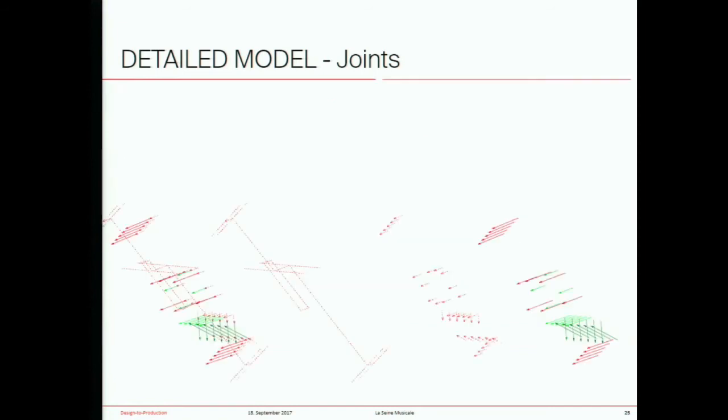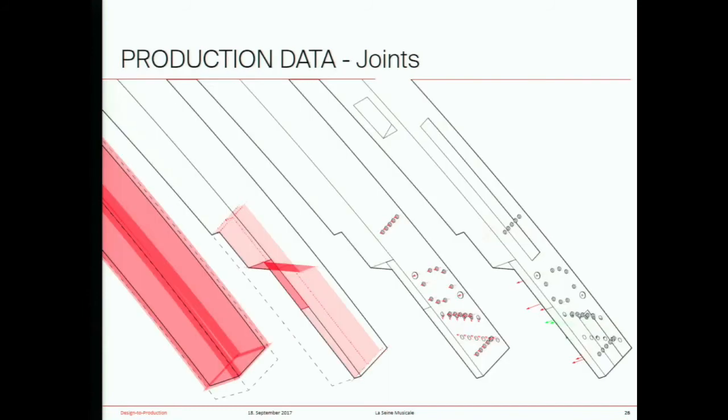At the end, all the operations are placed in the model at the reference level, which means that there's no margin applied yet. Instead, these tolerances are stored as attributes on the piece in order to be individually tweaked following the feedback that we receive from the workshop and the construction site. On such a project, the margin value usually hovers around 0.5 millimeter. This being done, the fabrication operations are translated into BTL format and passed to the fabricator to be milled.